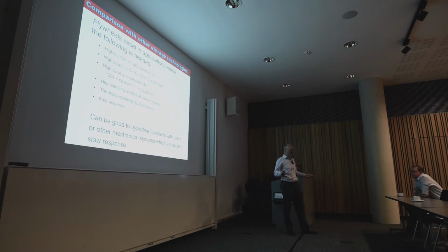If you want years of life, you're not going to get this from a battery, but if you have 1 cycle a day, then lithium ion is definitely better. The cycle life, we're talking of more than 20,000 cycles to infinity. If you keep the stress down, the design I've got is probably designed for 500,000 cycles. It's that kind of level. But it depends on the application. You have to do the analysis.